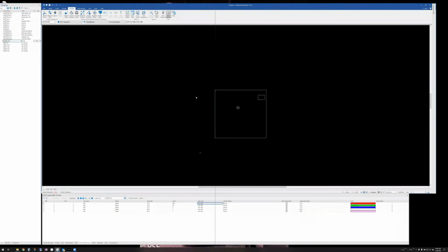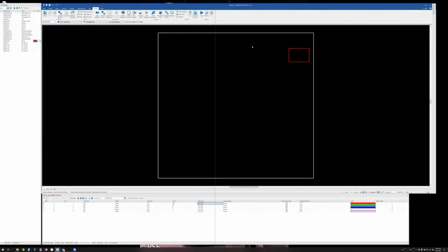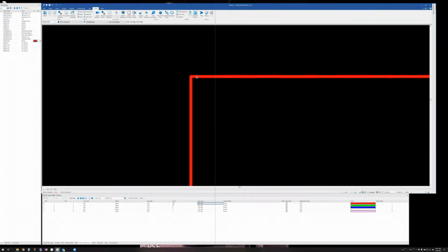When you load Gerber and NC, you may have a layer defined as a border, or it just might be on another layer. And what you can do is tell the software that the center of this border is the board edge. So we have a utility for that. It's under the Tools ribbon, right underneath it here, Draw Objects, Draw to Board Outline. So I just basically click on this, right click to confirm, say okay, and it adds that line in there.